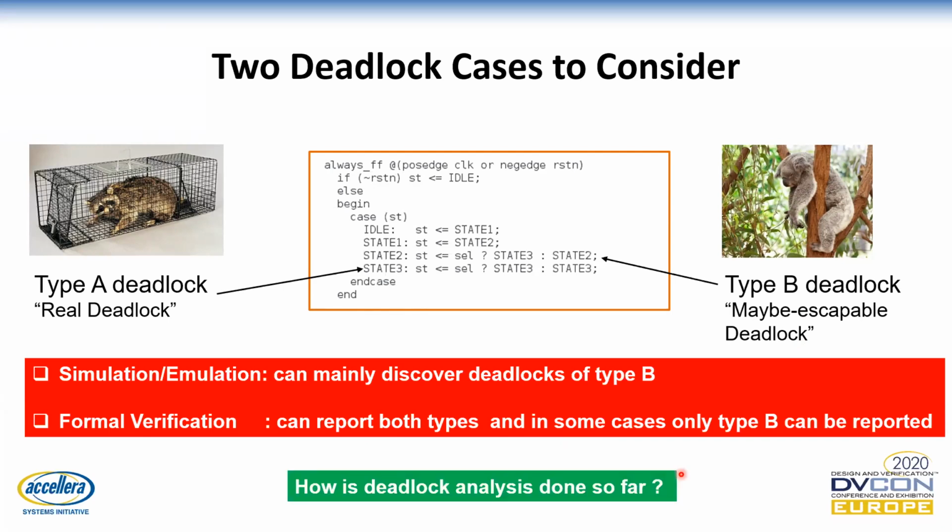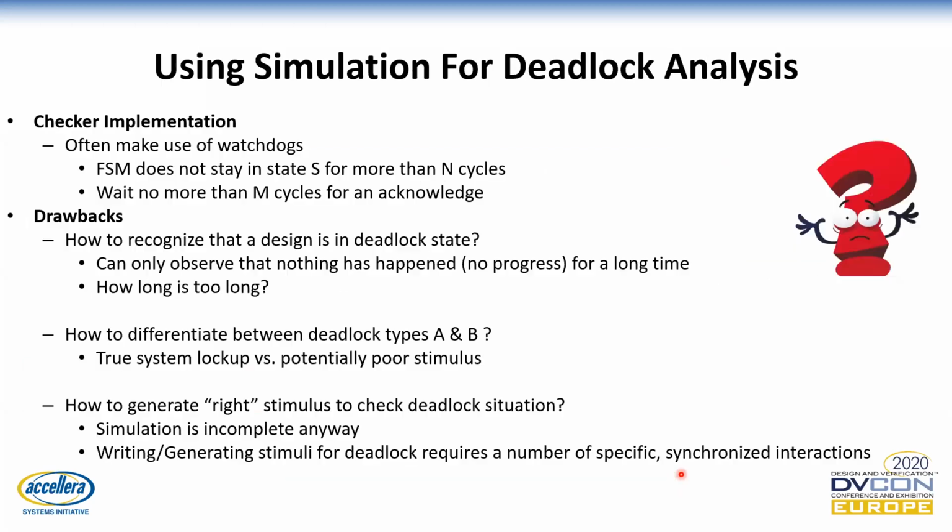Let's consider first how deadlock analysis is done so far. Simulation is actually the widely used solution for deadlock analysis. Deadlock checkers are often implemented as watchdogs in Verilog or VHDL. Watchdogs are mainly counting how long we stay in a state or how long we wait for an event to happen.